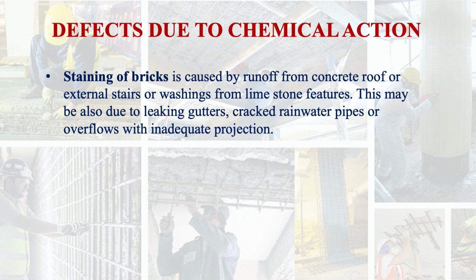Staining of bricks is caused by runoff from concrete roof or external stairs or washings from limestone features. This may also be due to leaking gutters, cracked rainwater pipes, or overflows with inadequate projection.